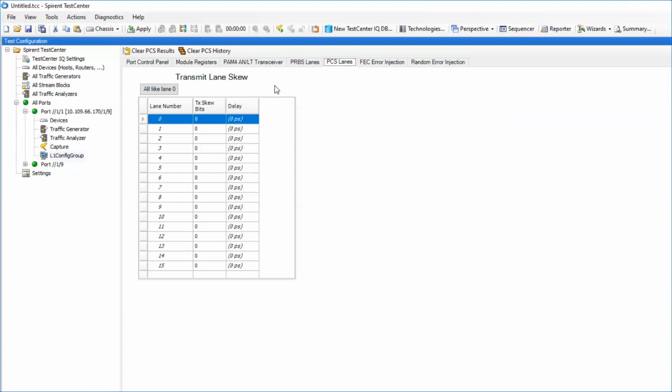The idea is that the port is a bigger pipe, say either 50 gig, 100 gig, 200 gig, but for transmit is divided into smaller paths or lanes. Then the receive side must rebuild the whole pipe by first realigning the individual lanes back to their original state. More or less skew per lane will have an impact on resyncing the lanes. So basically, you are testing the alignment logic for the port, meaning how well the port can find and lock on the alignment marker.